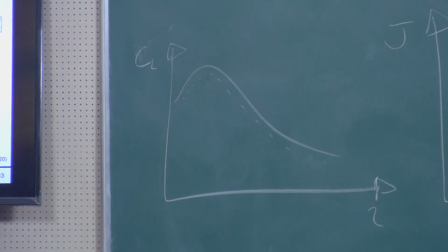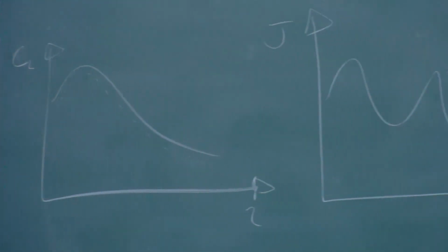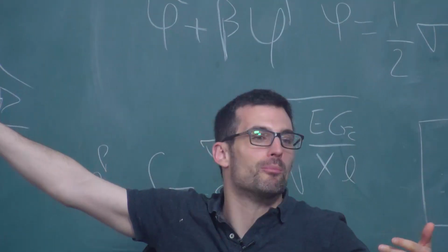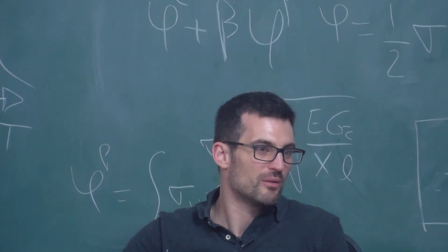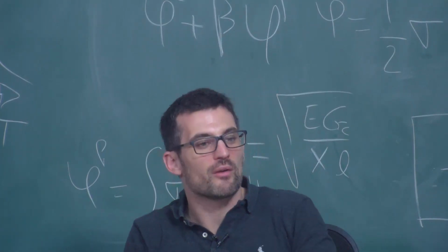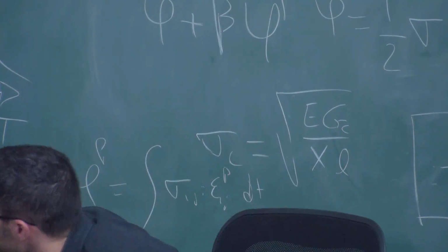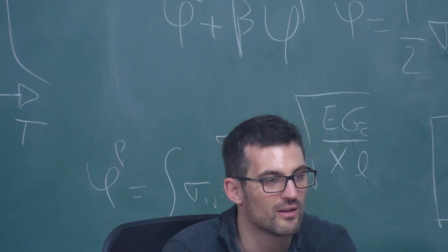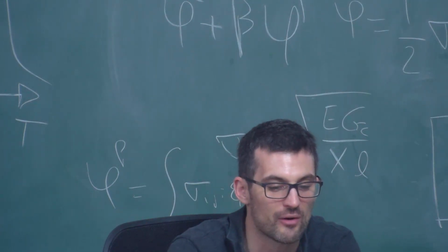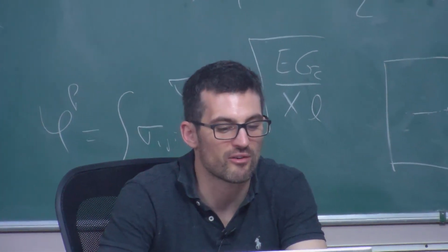I agree with it. But there's one aspect where it can play a role, and it's fatigue. Because, okay, yes, if you think of a pipeline standing there, then delaying things a few minutes is not going to change much, because the pipeline is going to be there for 50 years. But when you're dealing with fatigue, you have cycles of load, and as you can see here, because the hydrogen is following the hydrostatic stress, your hydrogen concentration is going up and down. So you have a frequency dependency.